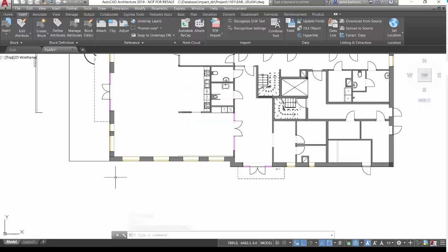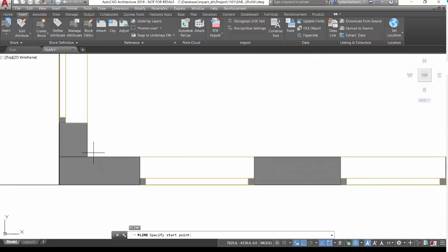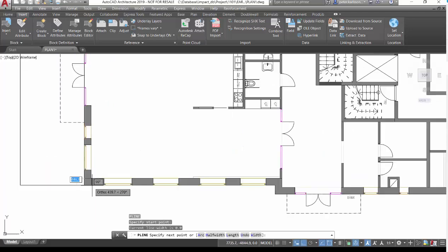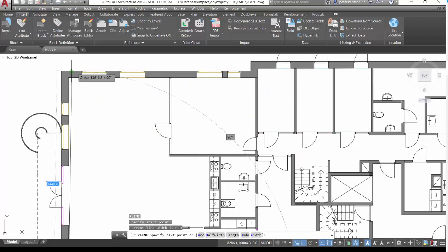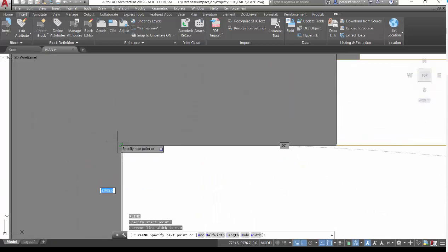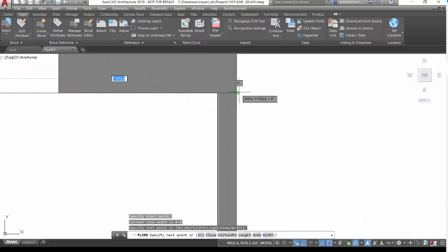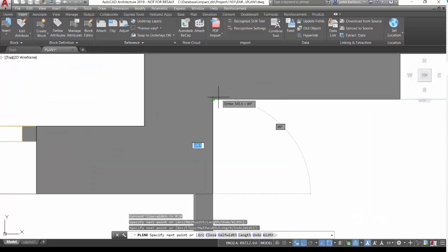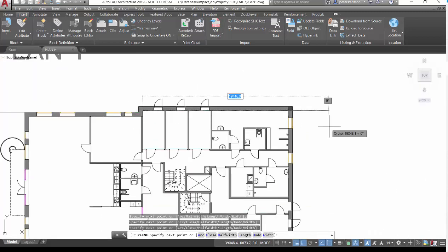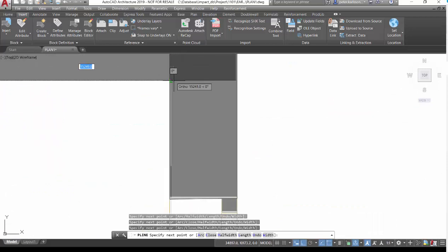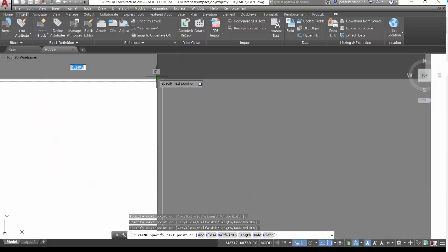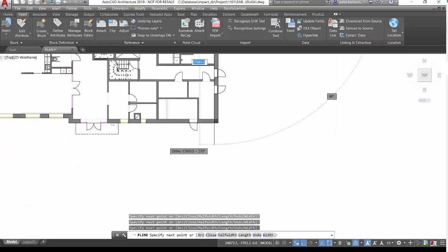So then I want to use the new command in Impact for drawing out wall outline. So then I need to draw some kind of, I think I do at least, a polyline to start with. So we have something what I want to make outline of. And now when I have this PDF made as object, it's very easy to snap on the points I mean. So I get the correct size of everything.